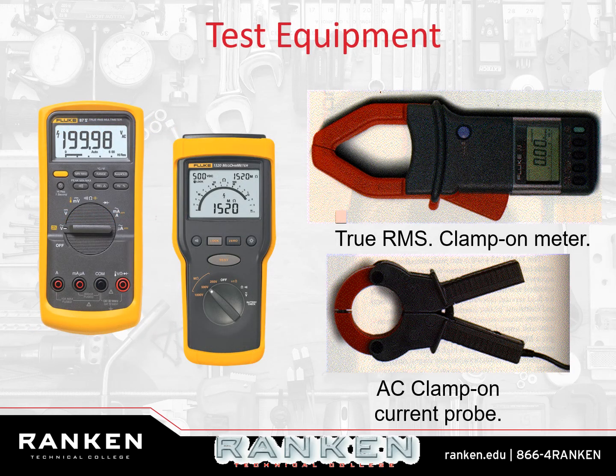Always, you're going to need your voltmeter, your fluke meter, let's call it. This one's a really, really good one. The one you guys get is also a really good one. A clamp meter or an amp meter of some sort, preferably a clamp on, is going to be required too. You need to check the current.